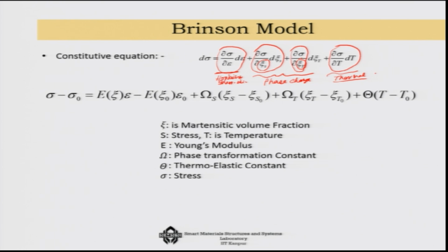Now, the effect of this constitutive relationship can also be expressed if we consider this ∂σ/∂ε to be a kind of slope. Instead of the differential form, if you want to use it as an algebraic relationship, then first of all, dσ would become σ minus σ0, where σ0 is the initial stress.